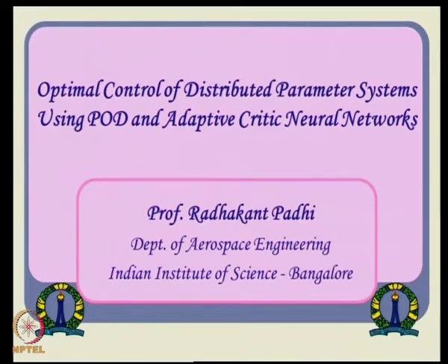But solution profiles themselves are a function of control, and hence they are not available before synthesizing the control, and that becomes a kind of a loop. Hence people have proposed something called re-POD and then online adaptive POD, all sorts of things. Anyway, we will not talk too much on that. We will assume that the closed loop system dynamics behavior can somewhat be captured in the representative solution set, and hence utilizing that solution set we can generate a POD basis function set.